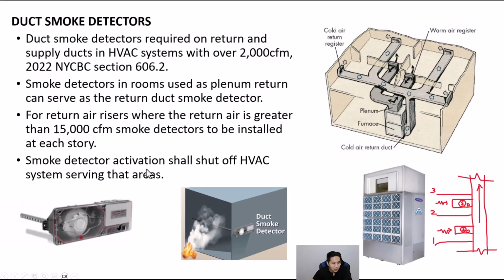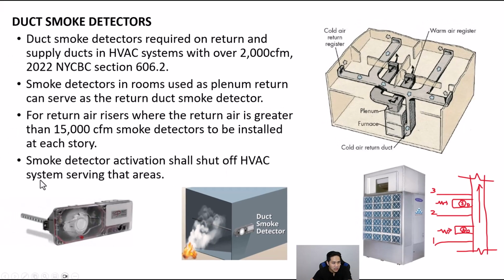Smoke detector activation shall shut off the HVAC system serving that area. So whenever one of those smoke detectors, either on the supply or return side, is activated, then you would have to shut off the HVAC system. And that basically is to prevent further spread of the smoke throughout that space.